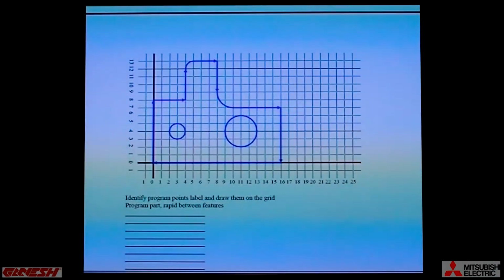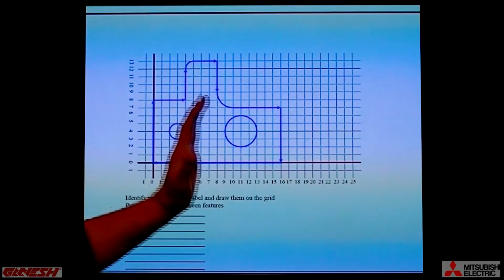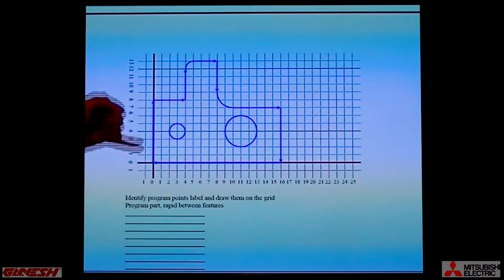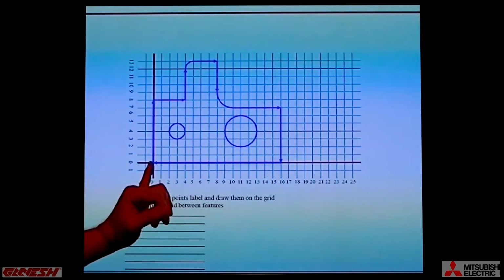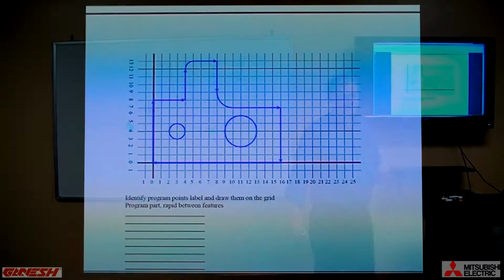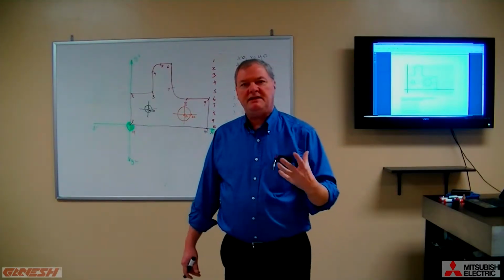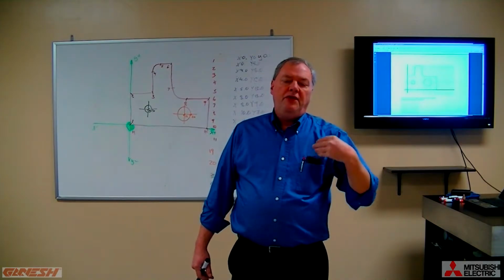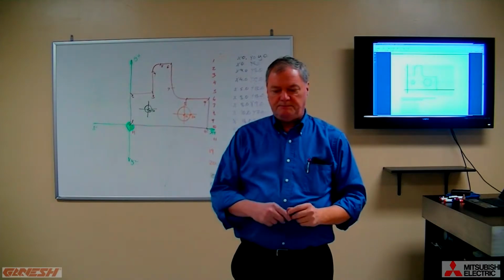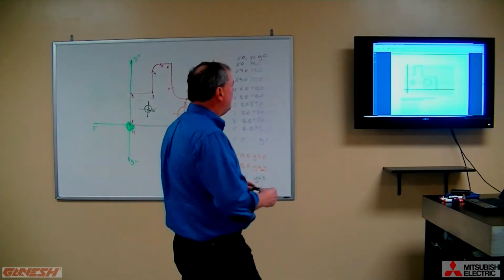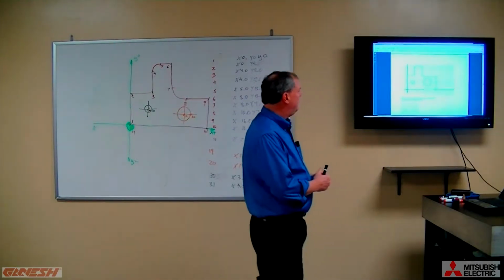Now, what we have to consider is an engineering drawing. As we looked at that, you'll see that dimensions on engineering drawings typically all come from a common point on a particular part. That's generally where we assign the datums, from a common point on the part that the dimensions stem from. They'll have reference surfaces and such. So this part just so happens to have the lower left-hand corner sitting right over our grid point datum.